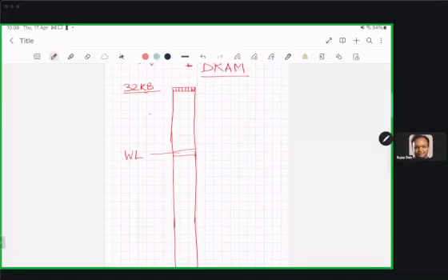Okay, so using this word line signal, I can select the row. Now here you see that if I build my memory like this, do you see any issue here? So basically 32 kilobyte of memory, I have put one word in each row, and I have a long, very skewed, skinny structure as my memory.